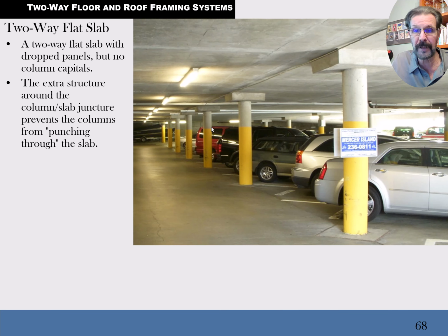They got that drop panel. They don't have a mushroom capital here, but they do have the drop panel, and that's giving them a way better way to distribute that load out further on that slab.